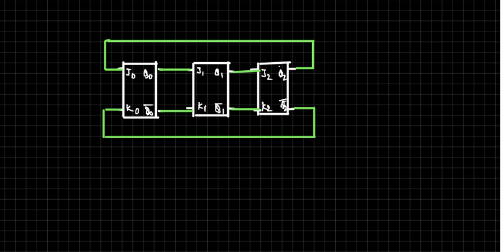That is called a ring counter. If the complement output is connected to the input of the first, that is called a twisted ring. That's it. Nothing fancy about it. These are also counters which are used. Just the states are limited. We can only count till n, the number of flip-flops, or at most up to 2n.